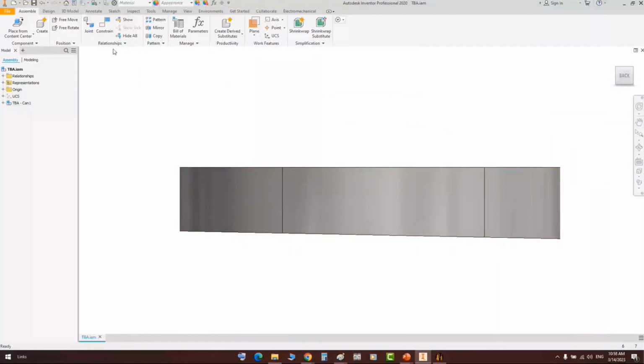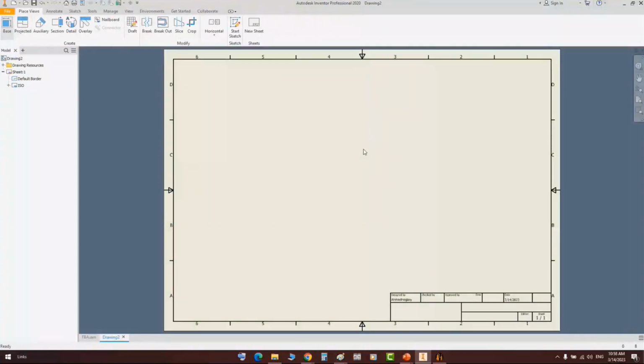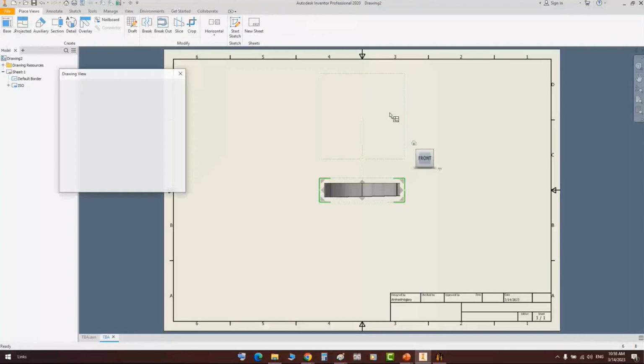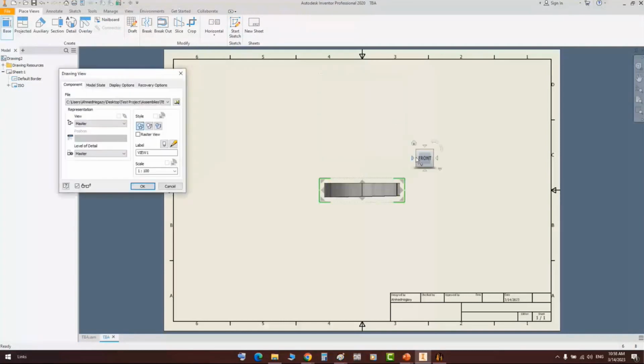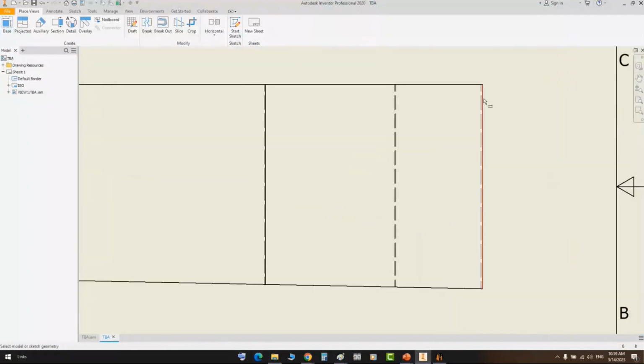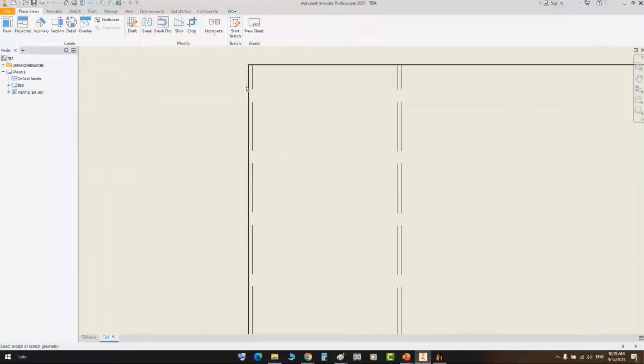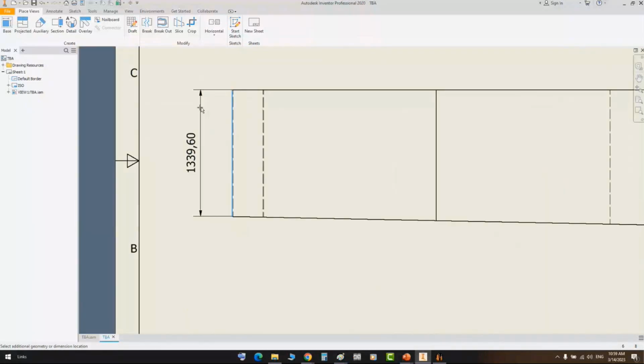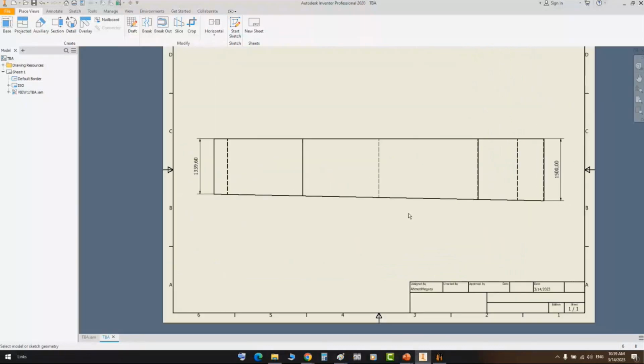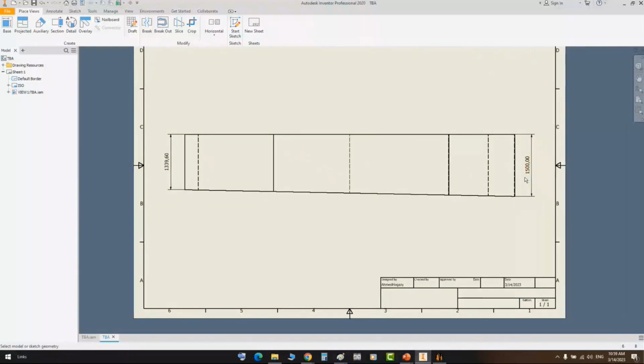Here, if we make a quick drawing and add a view from the back view, let's take a look from the back view and increase the scale up to 125, for example. Actually, you can figure that the height on this side, at 90 degrees, is different from the height on that side. So the bottom here is tilted. So you can use this type of shell in case you have a tilted bottom in a vertical tank.